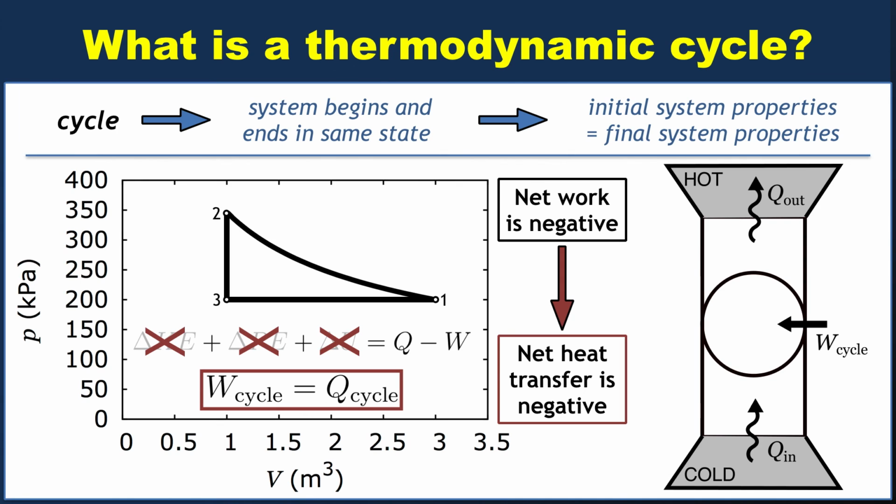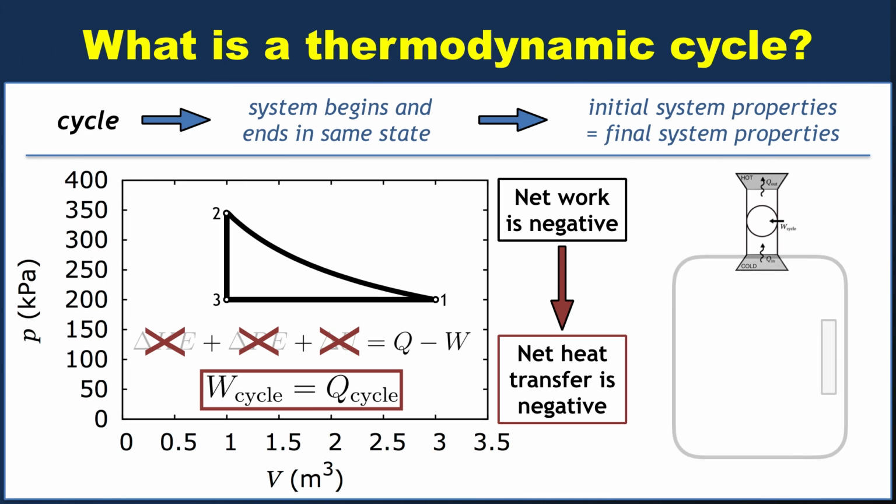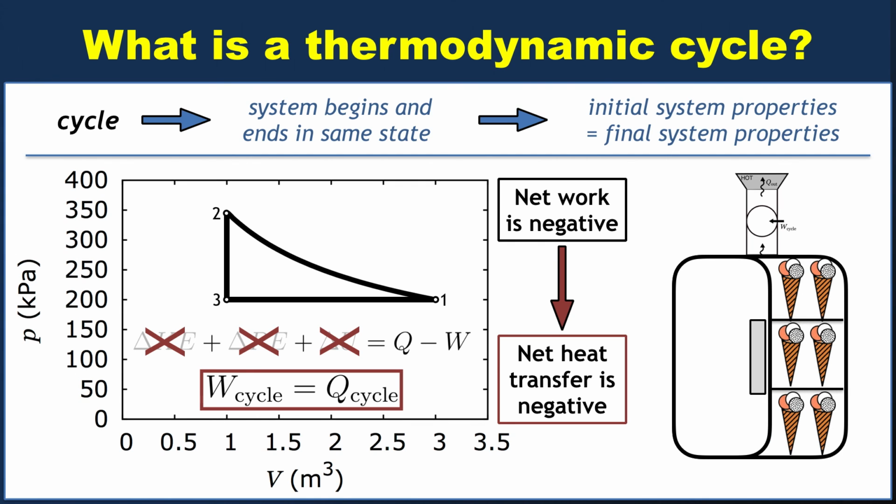Now you may think, what a wacky thermodynamic cycle, how would we ever use something like this? Purely speculative. Well, what if we miniaturize this and put it on top of a well-insulated box? Well, you can probably see where I'm going. We've made the cold reservoir into that insulated box, and if we open it up, sure enough, it's a refrigeration system. So the idea is that the reservoir is actually what you're trying to keep cold. The system itself is the motor attached to your refrigerator. The hot reservoir is, in most cases, the rest of your kitchen.